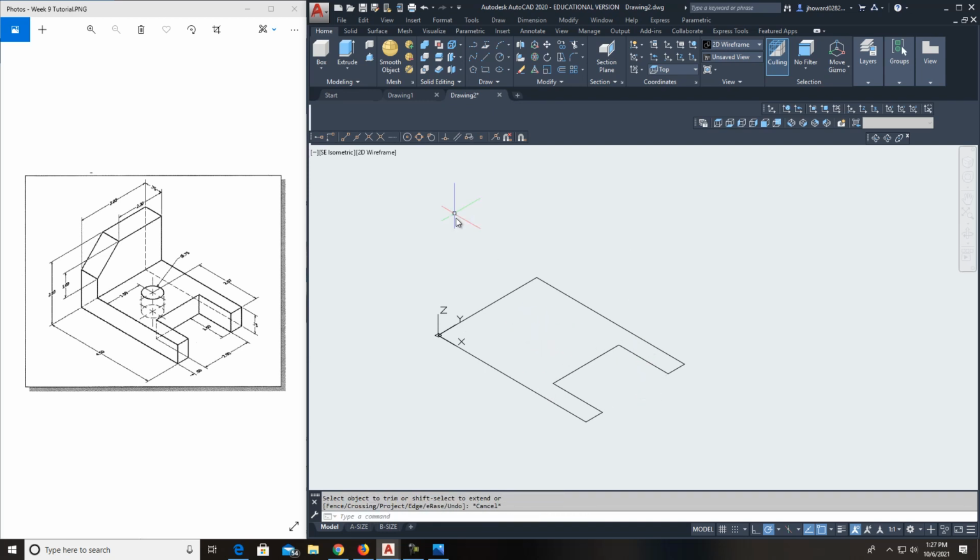Now, what I want to do is grab every bit of this and do a copy. This is my 0 point, and I want to bring it straight up. So what I do is hit at, 0 for X, 0 for Y, but now I have a Z axis I want to move. I want to move it at 0.75. So I do that, 0.75.